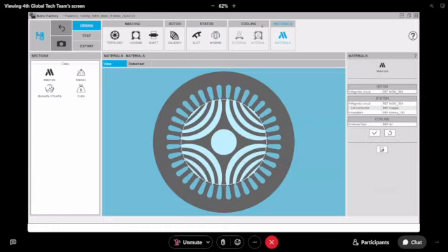You can see that there are cooling strategy, and housing and shaft. This is only interesting if you deal with the thermal computation, but for the moment, for the magnetic, topology, dimensions, slot, and so on are okay. Then you have to select the materials, the lamination for the stator and the rotor, and generally we use copper for the winding, and it's done.